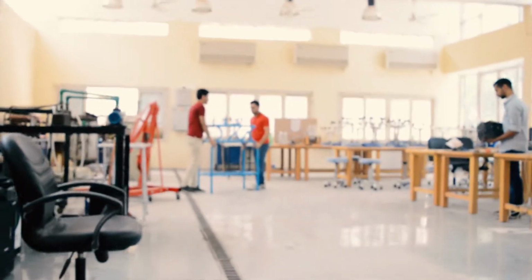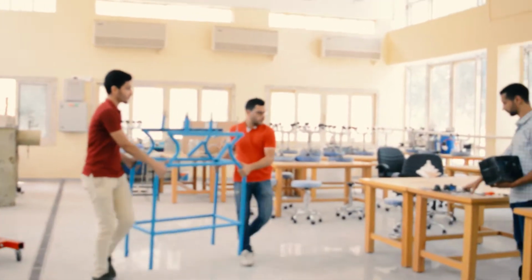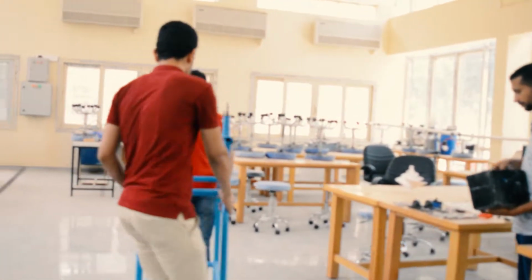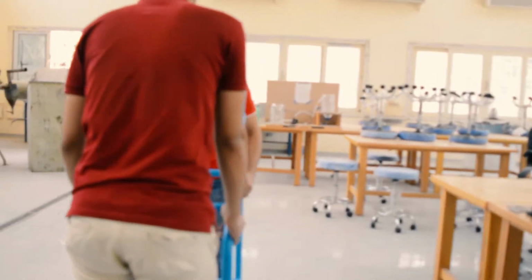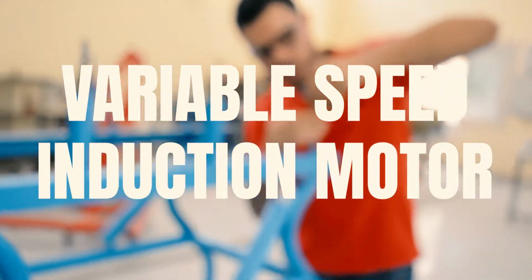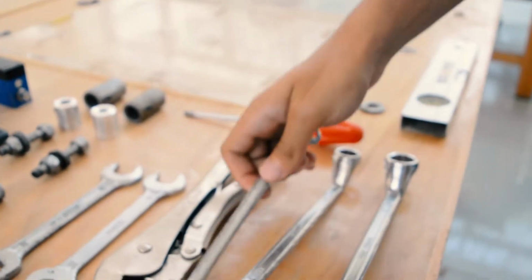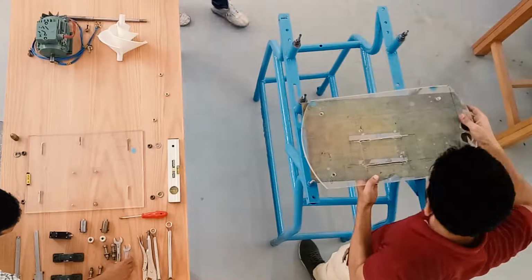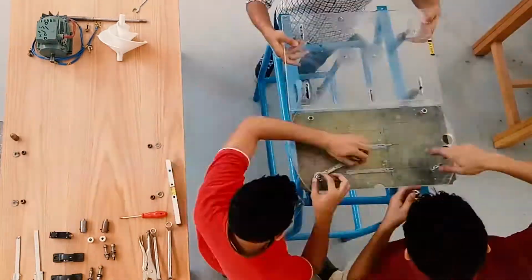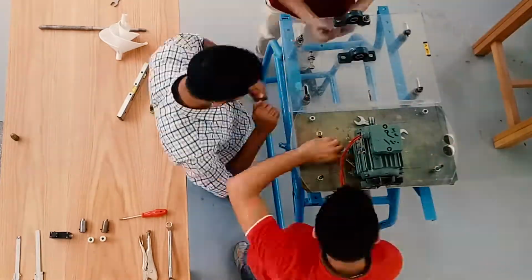To be able to make experimental operations on the wind turbine, we needed a test rig. The test rig consists of the turbine, a small variable speed induction motor, and a torque sensor connecting them all on one shaft. Building such a rig might seem as an easy task, but in practice, there are lots of factors that could make such a process a nightmare.